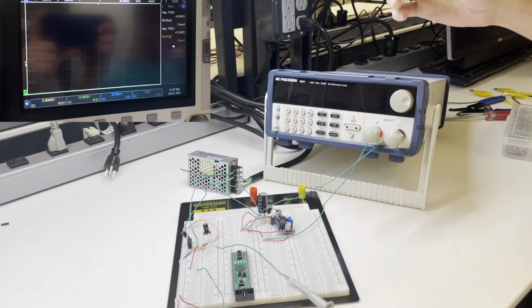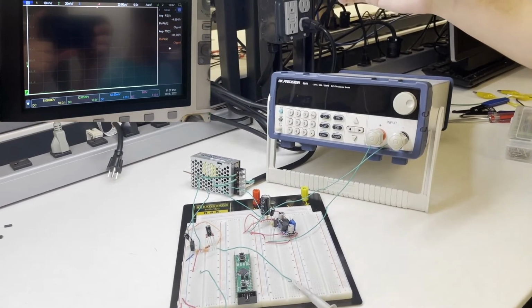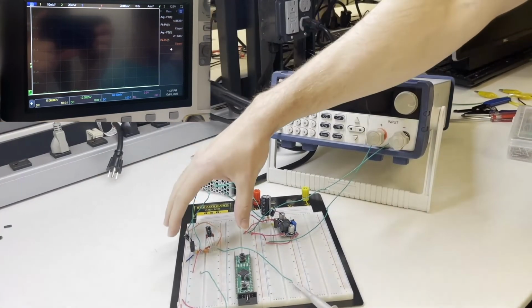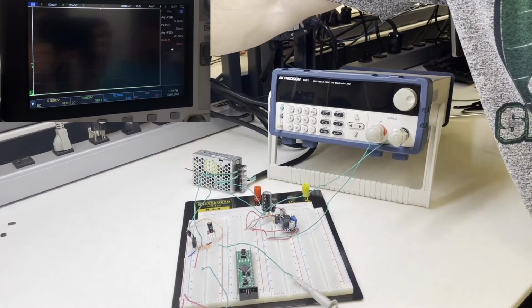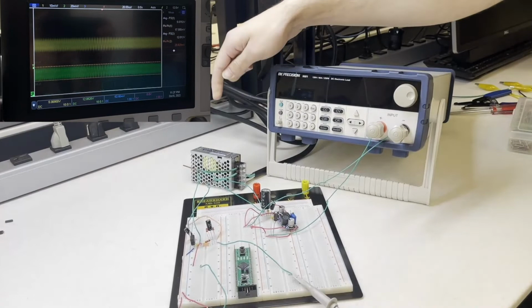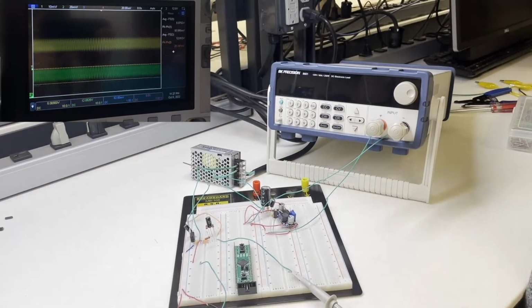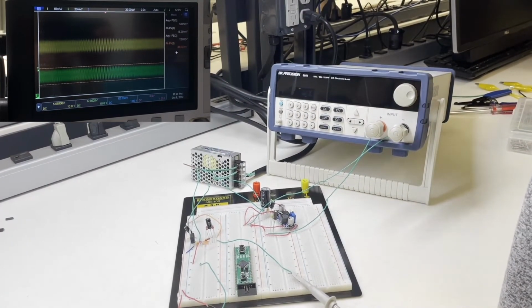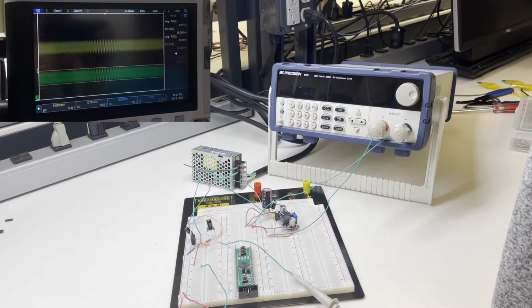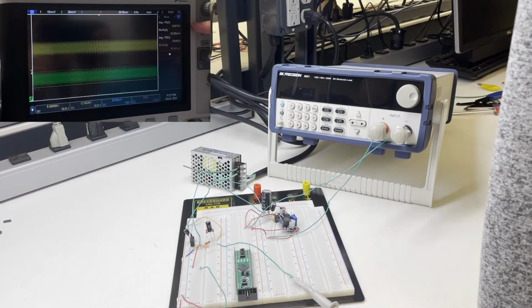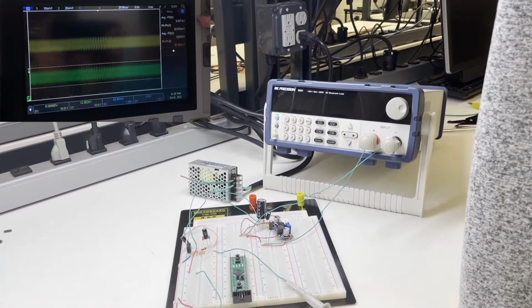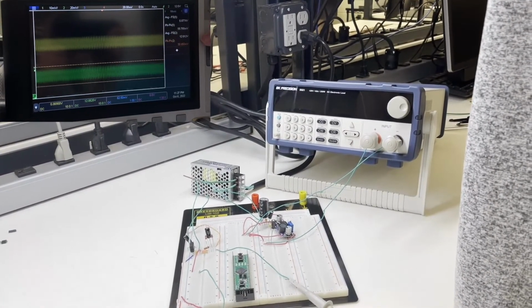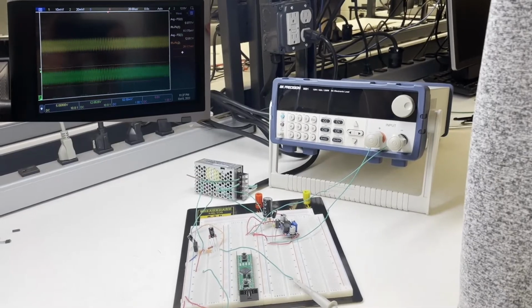Hello, this is Jared with the power supply subsystem. The first thing we're going to test is our linear regulator right here without the buck regulator. First thing we're going to do is plug it in. Power is going to go through our power converter and out through our linear regulator. As you can see through the oscilloscope here, we are getting the correct output voltage for both our power converter and the linear regulator, and our voltage ripple is below 1%.